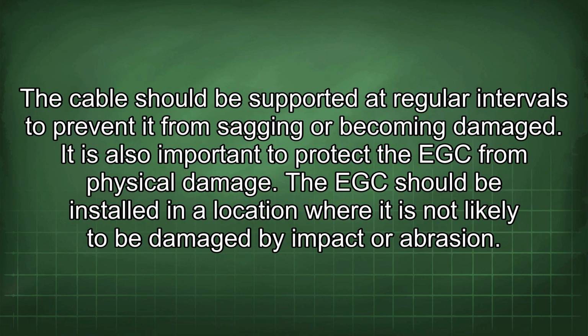The cable should be supported at regular intervals to prevent it from sagging or becoming damaged. It is also important to protect the EGC from physical damage. The EGC should be installed in a location where it is not likely to be damaged by impact or abrasion.